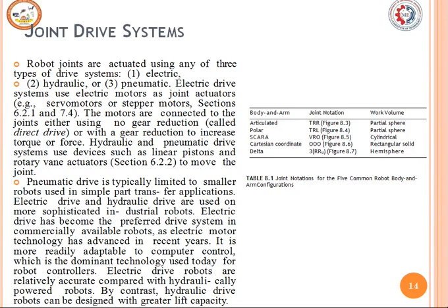The joints are driven with the help of drives: one is electric, second hydraulic and third pneumatic. For the electric drive, we are going to use different types of motors. It may be a servo motor or stepper motor. Based on the need, you are going to decide. Hydraulic and pneumatic drives use linear pistons and rotary vane actuators. If it is pneumatic, here air is used instead of water. So by pneumatic drive, we will be able to make the motions of the robotic arm structure easily.